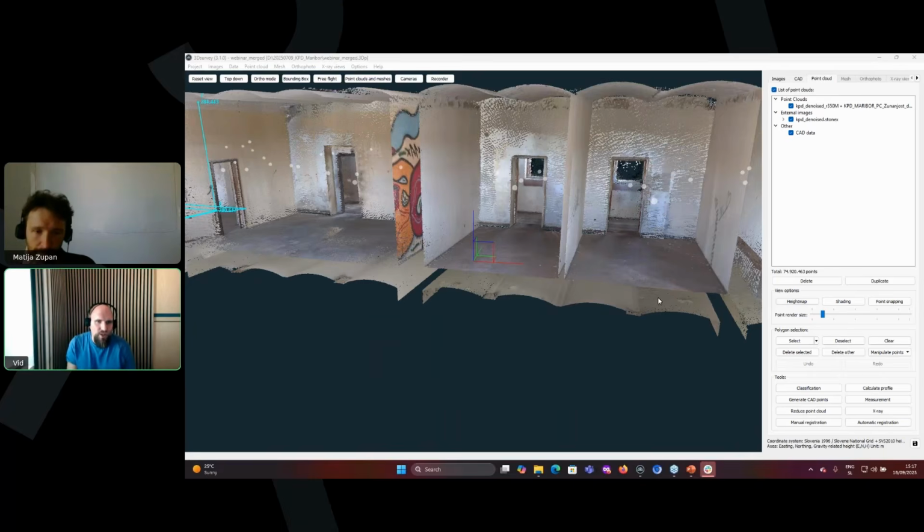But also in this one, we showed that in order to get a very detailed model, sometimes it's not 100% necessary to have thousands of images, because here for us 200 was enough. Of course, if your area is big, you will need a lot of images. But with one drone flight, you will maybe create 500 images. So if you're combining 5,000 images, that means you're putting together data from 10 different flights. The problem with that is that between those flights, shadows can move. It will take a few hours between different flights. When you merge them, some things can change. So sometimes that will also be the limitation. Why not put all the images into one project? It might make more sense to process the projects separately.